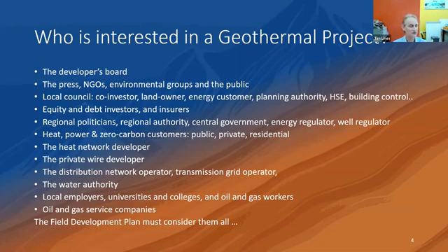Customers, perhaps the trickiest part of these developments is engaging with customers, whether they're heat or power, or indeed zero carbon, by which I mean some users are motivated because they need to acquire carbon credits or reduce their carbon footprint. The developers, heat and private, I've given you some more technical ones there. The distribution network operator, that's normally what you'd call the grid in most countries. And the transmission grid operator is the very high tension wire, maybe 132 kilovolts, that sort of thing. Surprisingly, the water authority, well, maybe not when you consider it, will be most interested in all your activities.